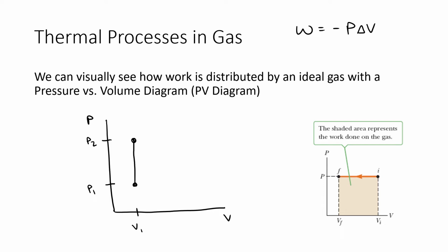By increasing the pressure alone, and if we kept the volume the same, we're not going to actually get any work done. We're not going to get any work out of this gas. So what's something else we could try to maybe produce some work? Remember, work is a force. Something has to actually move. So we could maybe keep the pressure the same, and we could increase the volume. That will make a straight line like this.